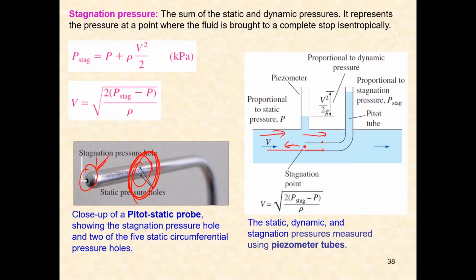So actually it's quite similar to the first tube here. It is perpendicular to where the flow is moving in this direction, so it's not going to be affected by the velocity. So this is the pitot tube. This captures the stagnation pressure, which means that it's capturing both dynamic and static pressure, and this one is capturing static only. So how do you want to find the velocity?